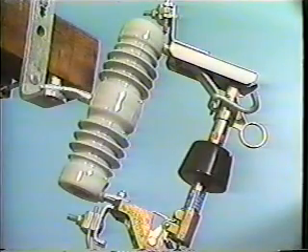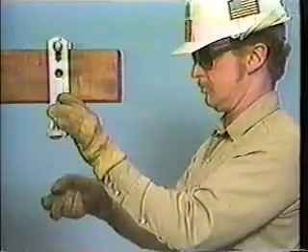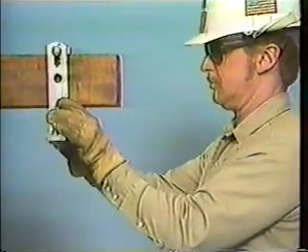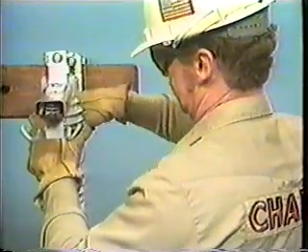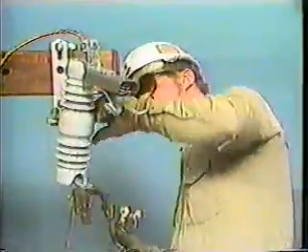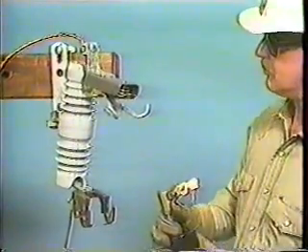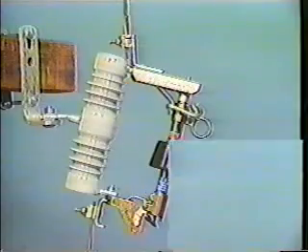The CES unit mounts in a standard Chance Type C cutout and also in the S&C Type XS cutout mounting. If the application is to replace an existing fuse cutout of these two manufacturers, then the electronic module, being interchangeable, will simply replace the cutout fuse tube. If the application is a new installation, then the mounting assembly and electronic module are installed as a unit using the same installation procedures approved by your company for installing cutouts.